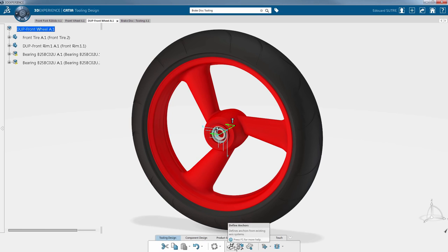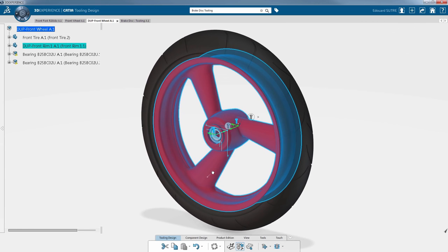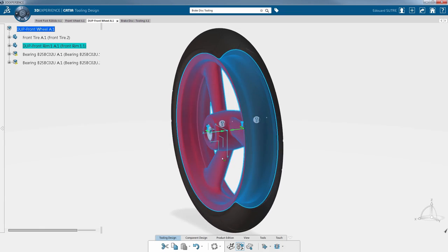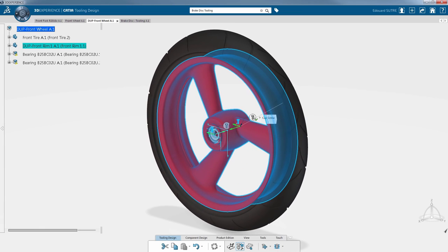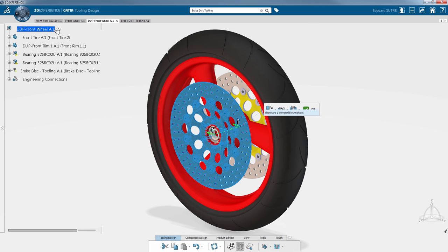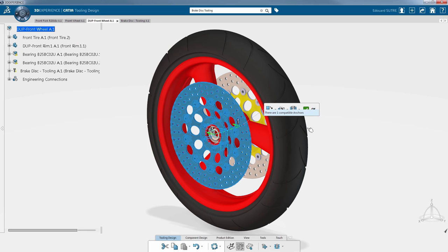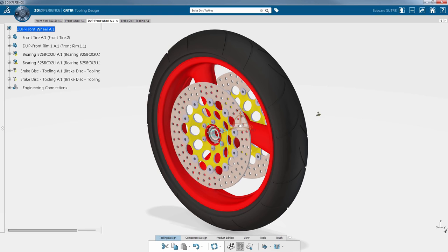We insert the brake disc assembly in the front wheel product using the component placement command. Select the receiving part, the red rim in this case, the interface to populate, two possible anchors are available, and the component to insert from your current session or search results. In one click, all the available anchors have been automatically used. You may only instantiate an element compatible with the selected interface or anchor. It prevents unwanted manipulations and mistakes in assembly.